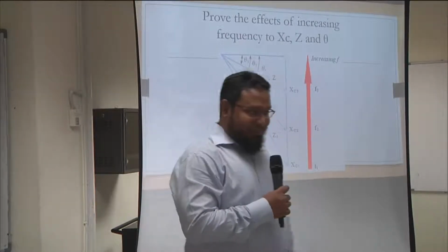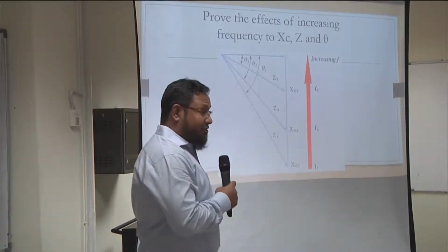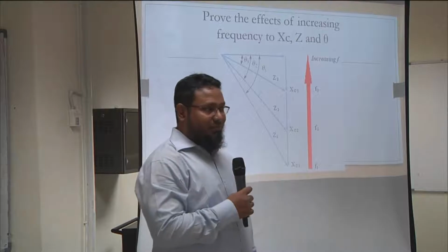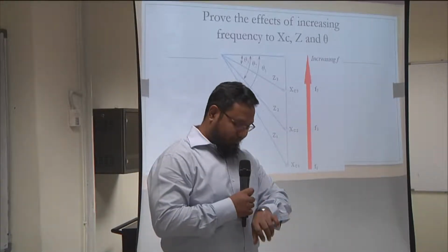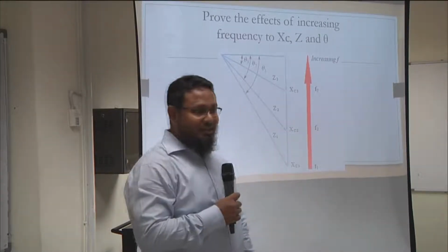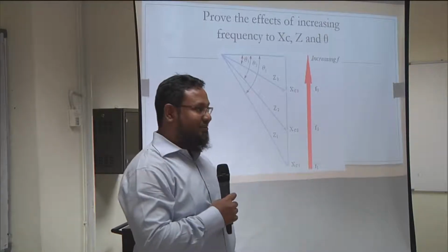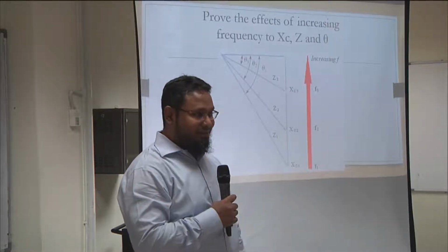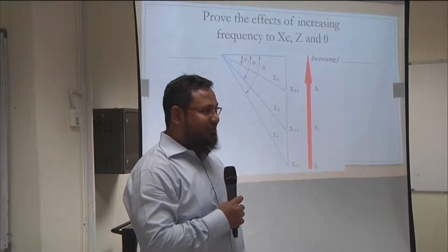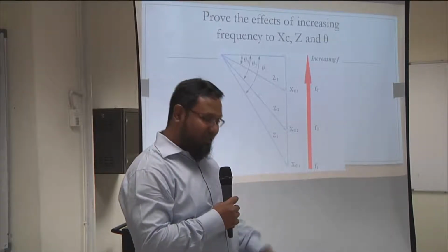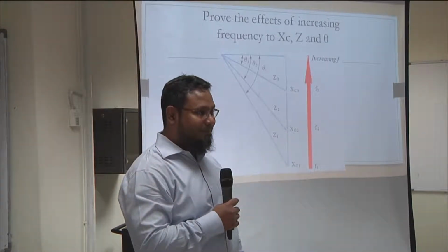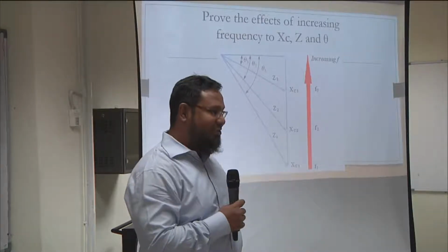Okay, so let me ask you this now. In case of inductors, we already know the impedance is j omega L, right? So in case of infinite omega, what do you think the value of the impedance is going to be? Impedance due to the inductor. Infinite. j omega L, infinite.